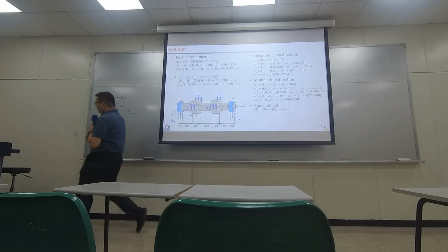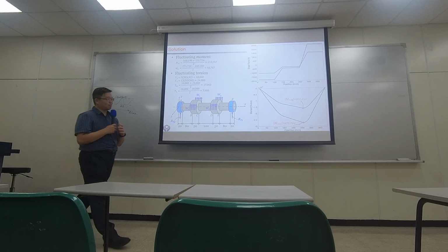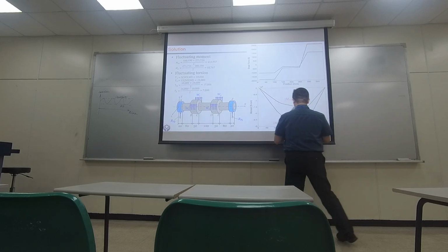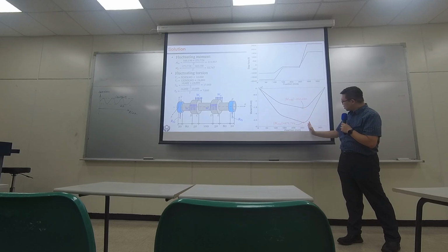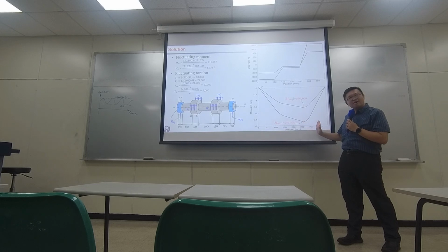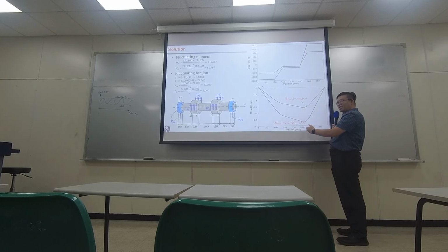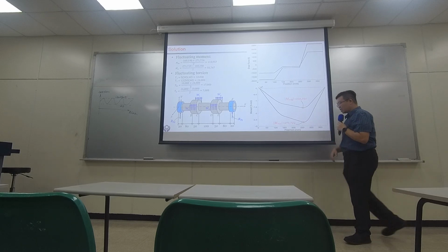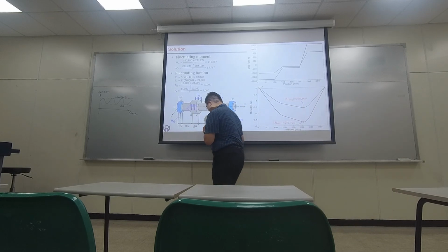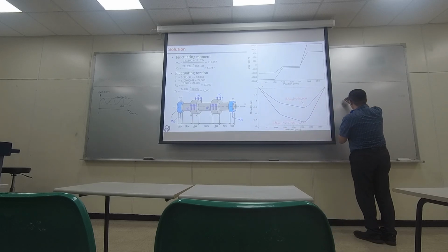However, if you observe from the figure, you realize they are actually not at the same position. It's slightly located at a different position, but it's very close. So around this area in the shaft, it's always carrying the largest bending moment, slightly shifting left and right in the two conditions. So if I make a drawing of the shaft, let's say this is a shaft.